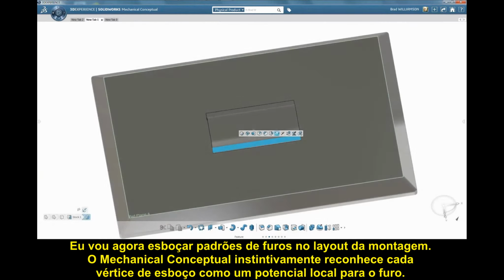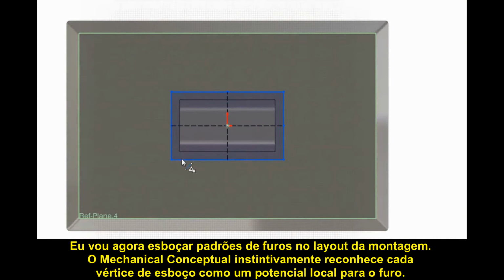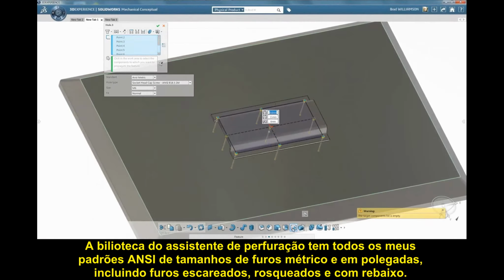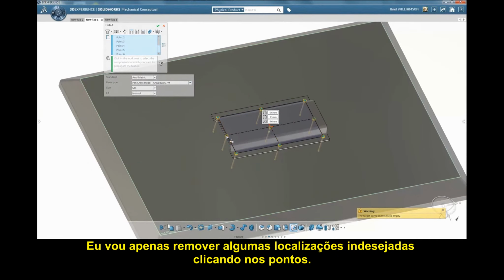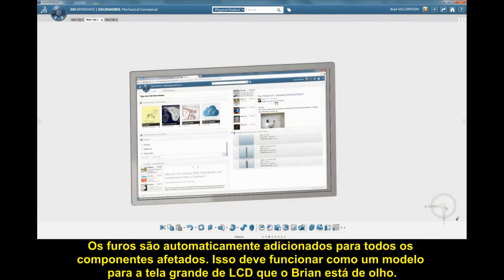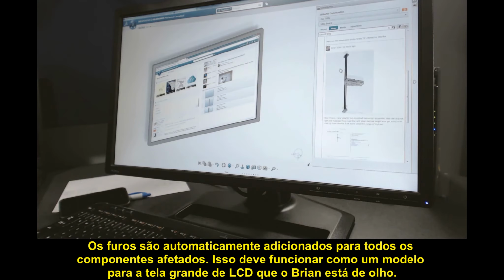I'll now sketch in the mounting hole pattern on the assembly layout. Mechanical Conceptual instinctively recognizes each sketch vertex as a potential hole location. The Hole Wizard library has all my standard ANSI inch and metric hole sizes, including taps, countersinks, and counterbores. I'll just remove a couple of the unwanted locations by clicking on the points. The holes are automatically added to all the affected components. This should work as a mock-up for the large screen LCD that Brian has his eye on.